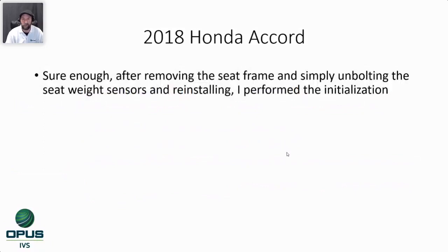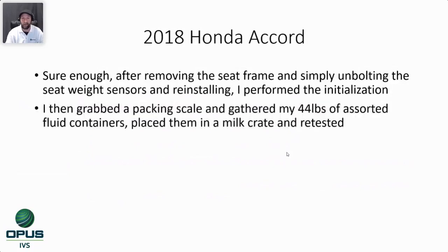So sure enough, after I removed the seat frame and unbolted the seat weight sensors and reinstalled them, I performed the initialization again. I grabbed a packing scale just to verify. I grabbed 44 pounds of assorted containers that I found around the shop there. I have a packing scale.